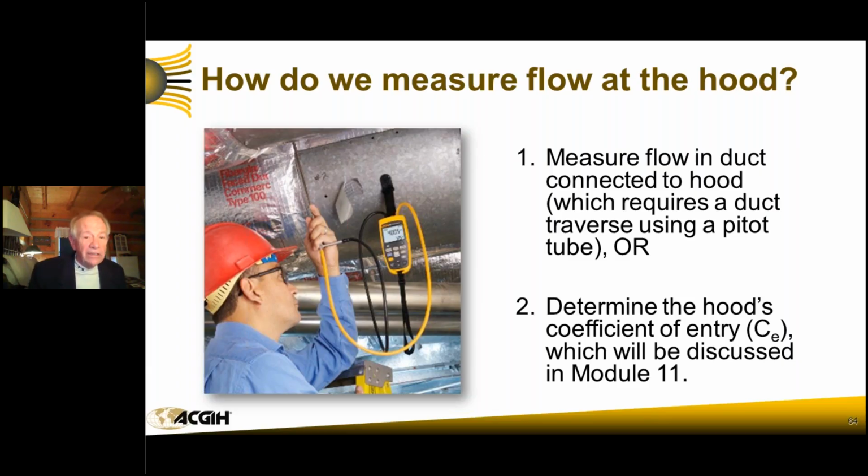and volumetric flow rates. The C sub E can determine the volumetric flow rate with one static pressure measurement after a thorough inspection and quantification of the hood's volumetric flow rate is done one time. Once you do it once, you can come back, take a static pressure measurement, and you'll know what the CFM is from then on. And you can train your technicians to do it. And if you have more than 20 hoods that are alike, and you don't use the C sub E, then you are doing yourself such a disservice. I can't tell you.